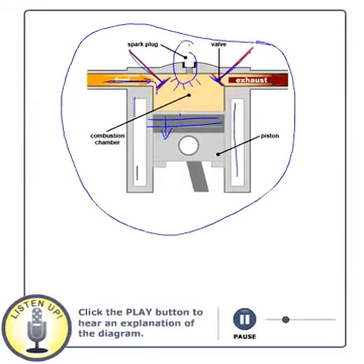This acts like a syringe, a medical syringe. When we push this down, the fuel and air mixture is basically sucked in, and it fills up this entire volume as this piston comes down. That is the first step or stroke. This is a 4-stroke engine that we are talking about. First stroke is intake.